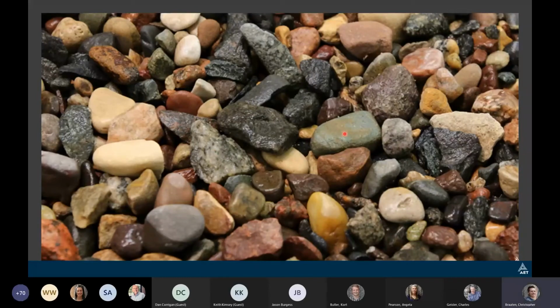Over here, you can see this particle. It's a little rounded, a little dull, a little earthy. You're going to want to double check that particle. I'm going to take that and scratch it and see how soft it might be. We use a weighted brass pencil. I think it provides 2 newtons of force. So it's supposed to take out any strength differences between the people performing the test, right? You might have one person who is really, really strong and can dig a Mohs hardness of 3 right through that, and you might have somebody who's not as strong, who might not be able to scratch it because they can't put enough force on it. So it takes that part out of it. So we'll use that weighted pencil and see if it can provide a deep scratch, and then we'll qualify that as a soft particle.